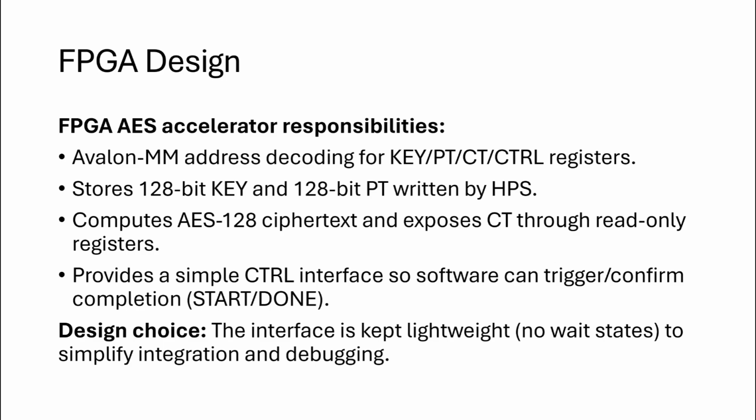The ciphertext is exposed in the read-only CT registers, and we provide a simple CTRL interface so software can trigger encryption and confirm completion using start and done. As a design choice, we keep the interface lightweight with no wait states to simplify integration and debugging.